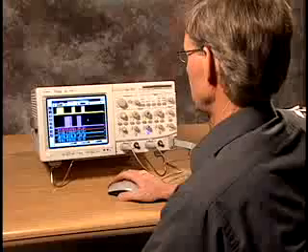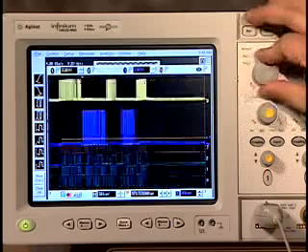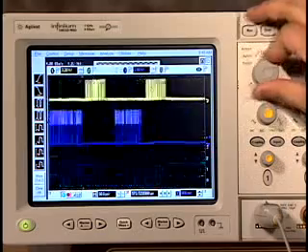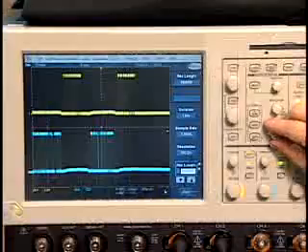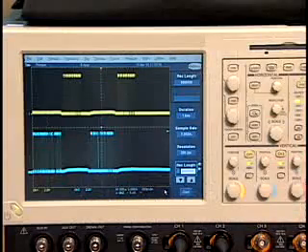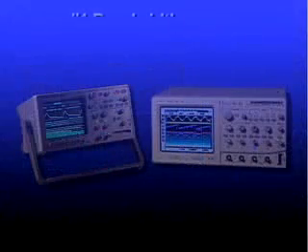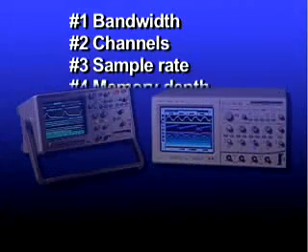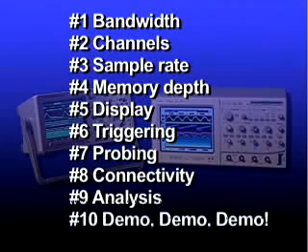Also, pay close attention to a scope's display responsiveness. When you change the volts per division, time per division, memory depth, and position settings, does the scope respond quickly? Try the same evaluation with measurement features turned on. Is response noticeably slower? Once careful and comparative consideration of all key issues is achieved, you should have a much better and more confident idea of which oscilloscope model meets your needs.